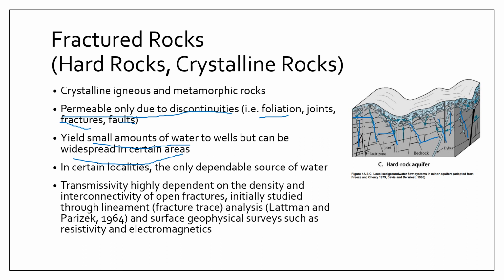The importance of hard rock or crystalline rock aquifers is that there are certain localities where your only source of water are these crystalline rock aquifers, right? And it has been studied before that the transmissivity, or the ability of the aquifer to transmit water, is highly dependent on the number of your discontinuities as well as their interconnectivity.